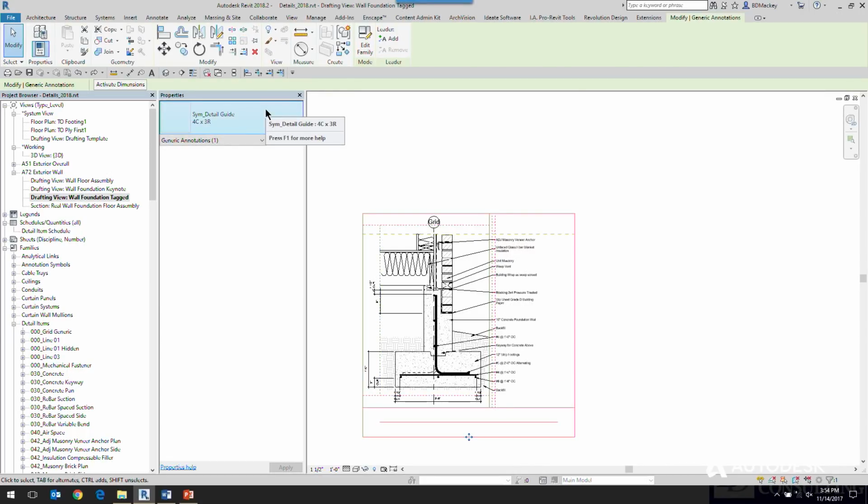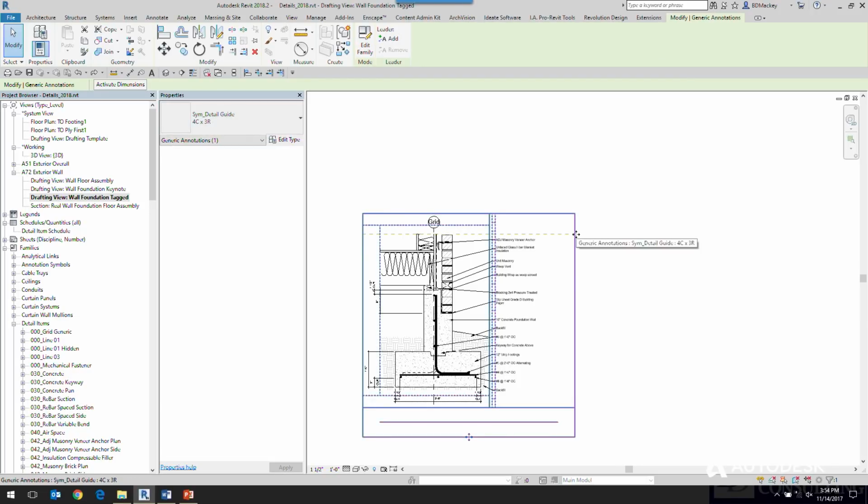I'll have one on a real project that's 1 column by 1 row. So when I'm working on a floor plan, I just drop this on the floor plan, and it shows me how big my floor plan needs to be. So I'm not doing the back and forth: drag it onto a sheet, change a crop region, switch back and forth between the view, deactivate view. Oh, does it fit? Move it around. I use this little guide just to show me how big this layout is going to be.